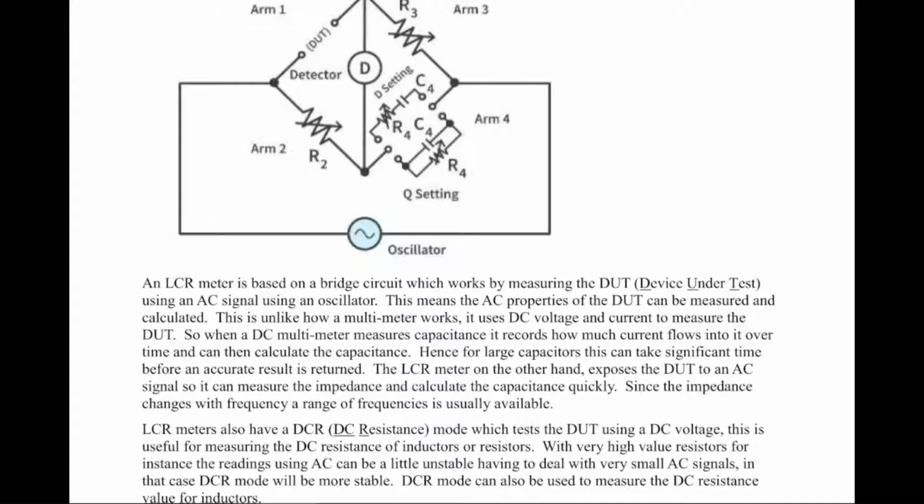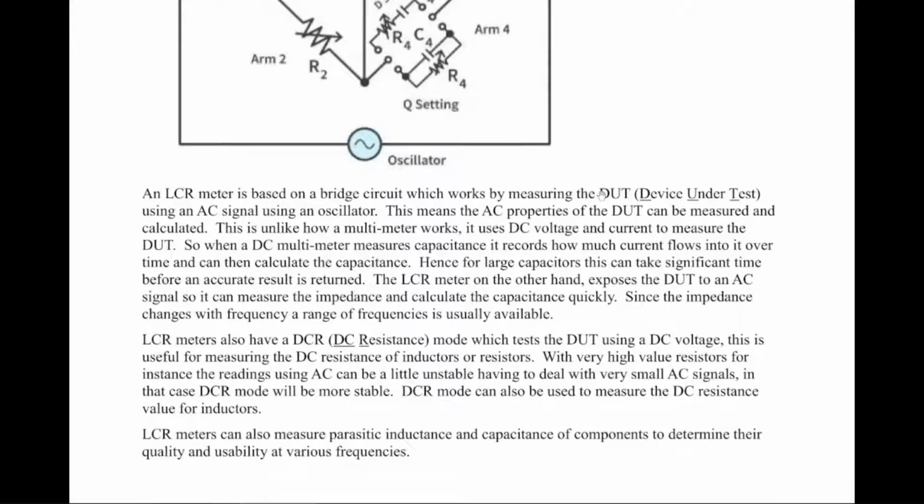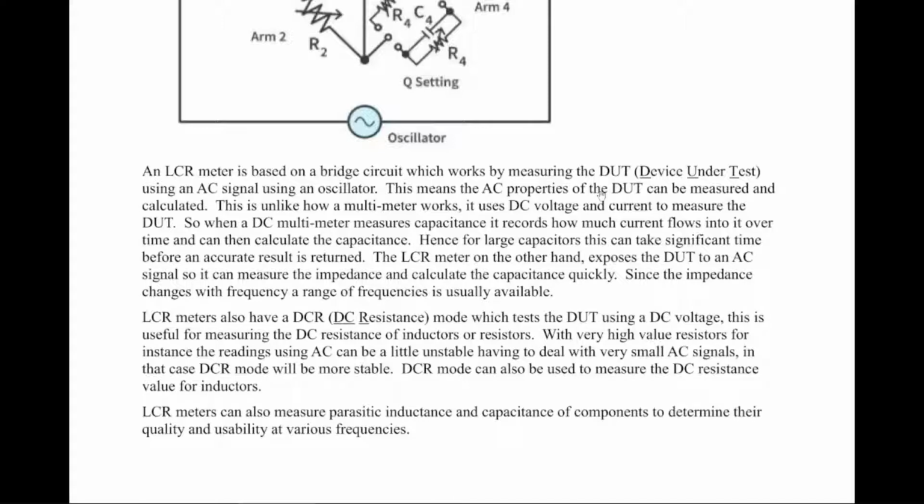In a similar way like we showed on the oscilloscope, it can also calculate the trailing or lagging of the voltage and current and come up with the phase angle. And the values that we want to know, like in henries and farads and ohms and so on, it can measure some of those directly, and others it can calculate and display.